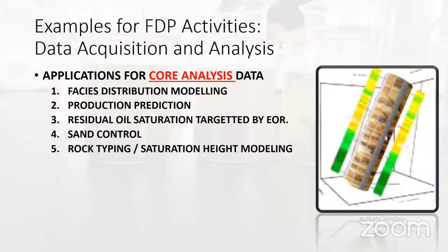Good modeling for the rock typing and its distribution in your 3D model, and also the saturation height modeling for calculating the oil in place and the original gas in place. So if there is no data about the reservoir rock properties, you don't have very efficient planning for the development of your reservoir.